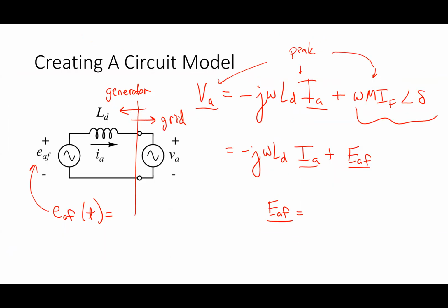Let's go back to our picture. Let's look at the electrical side. I don't have control in the real world over what omega is. I don't have control over what VA is. VA is the grid. The grid is fixed, right? I don't have control over the current necessarily directly either. What thing can I easily control? I sub F. I can control one of the currents, I can't control both of them, right? When you guys said the current, I was thinking I sub A, but I sub F is the one thing I have control over. I sub A follows whatever it's being told to do.